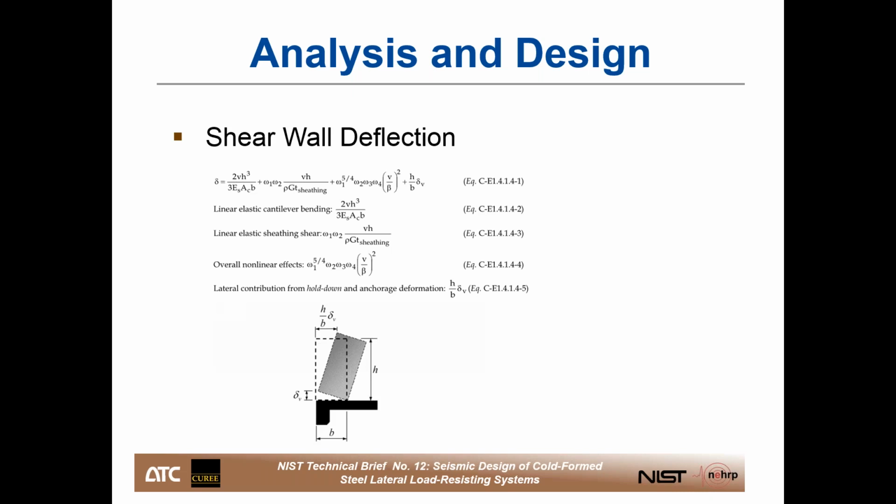but it also makes design of these systems iterative when you have to rely on the rigidity of the shear wall to determine forces. So for example, in a rigid or semi-rigid shear wall situation, what you end up finding is that the stiffness of the shear wall is dependent on the force in the shear wall. So you have to iterate around and around to zero in on a solution where everything is aligned with regard to forces and deformations. It is our hope and intent that in the next code cycle we can fix that and actually come up with a linear elastic deflection equation that can then be used to more easily design to and be more consistent with ASCE 7's notion of the deformation amplifications.